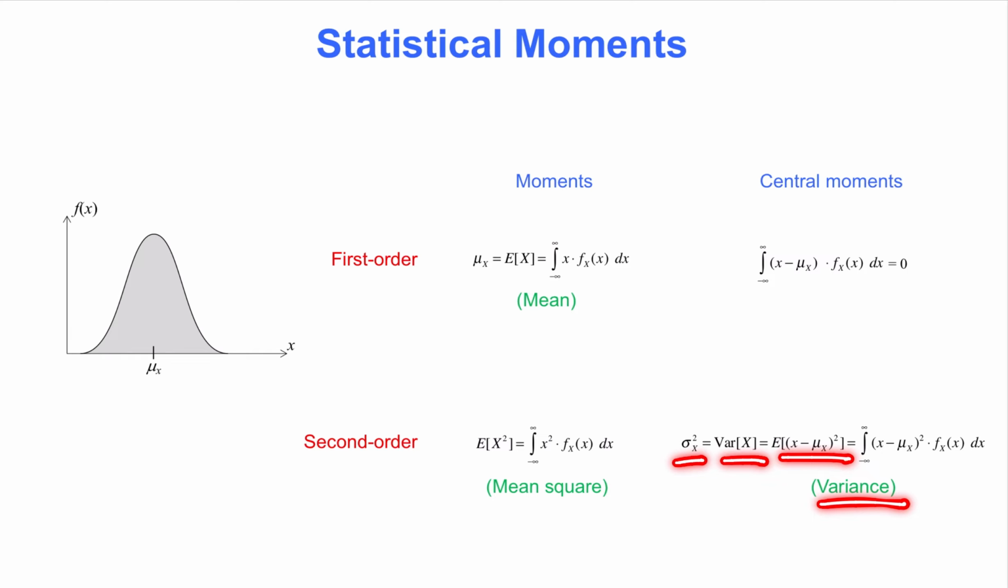Before we leave this slide, we can explain phrases that appear in structural reliability analysis. One phrase is second moment information, another is second moment methods. From what we have learned on this slide, those phrases imply that we use only partial descriptors of the random variables, instead of the full distribution, and that we include partial descriptors up to the standard deviation, but not higher order moments. This means that second moment methods work with the mean and standard deviation of the variables, and also the correlation coefficient, which is introduced in the video on joint probability distributions.